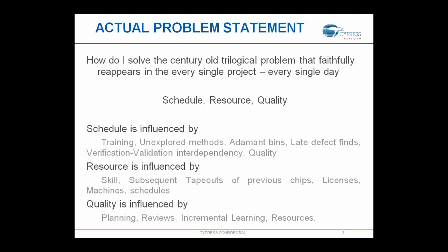Verification and validation interdependency. There are lots of protocols these days where a timeout should happen at 32 seconds. Come on, we cannot simulate 32 seconds, right? So we need other dependencies to understand whether the counter rolled over properly, and whether the terminal count was used properly to issue a timeout. Those things cannot be verified in simulation, so we have to depend heavily on validation to do that.